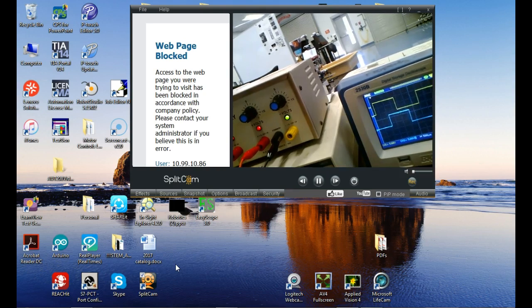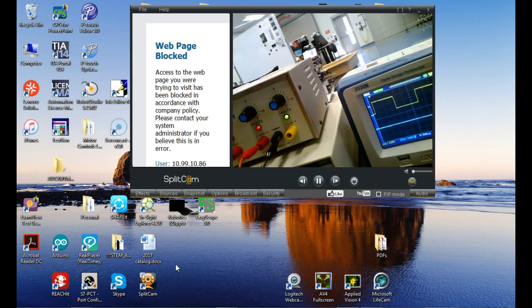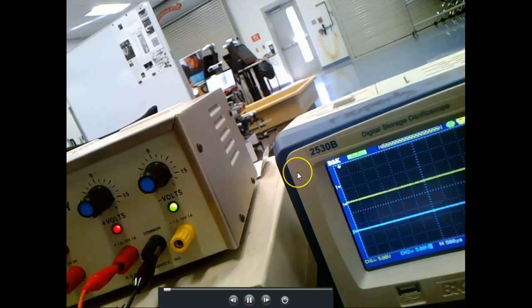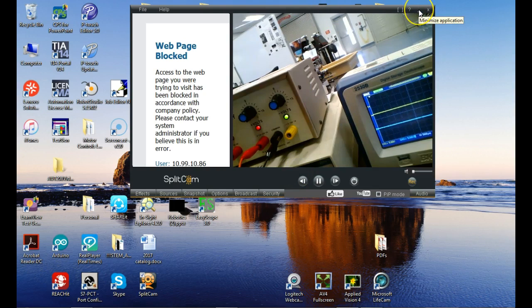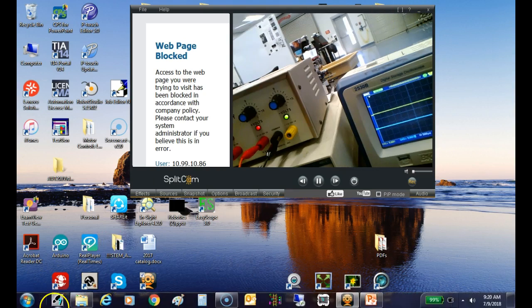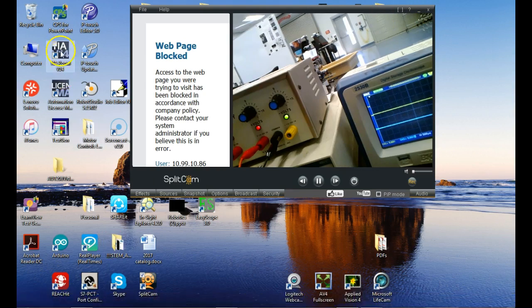So this would indicate one direction, and I can't flip it on the oscilloscope, it always would be the same. So if I reverse the direction of the motor, then they would shift position. I can't show that on the oscilloscope because the oscilloscope always references to one channel. So everybody follow me so far?